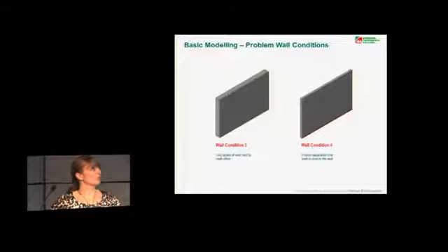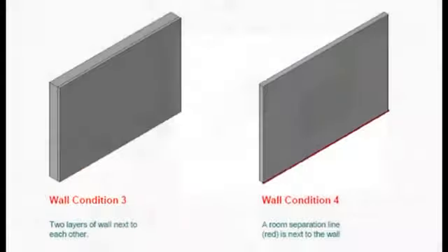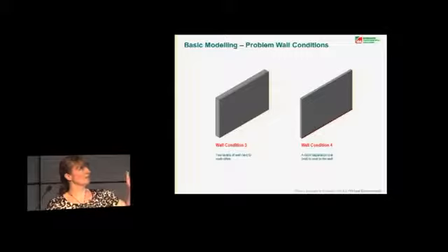Building layers of construction, again, will create the same sort of result. It will take the inner surface of that to be the wall, and then it will take the external layer to be a shading surface. What we would do there is to set that internal layer to be non-room bounding, okay? We actually define constructions not by building them as individual layers; we just define them by the materials that they're made up of and the thicknesses.